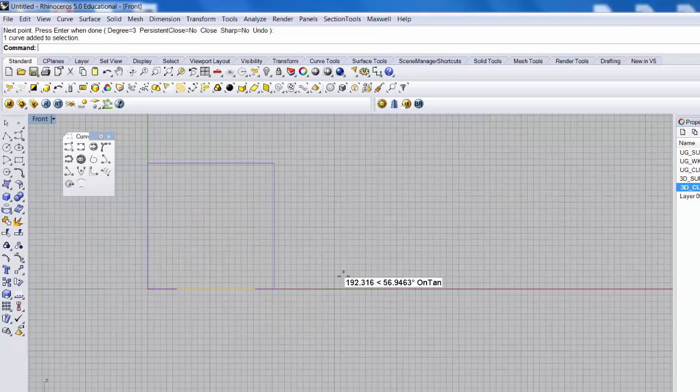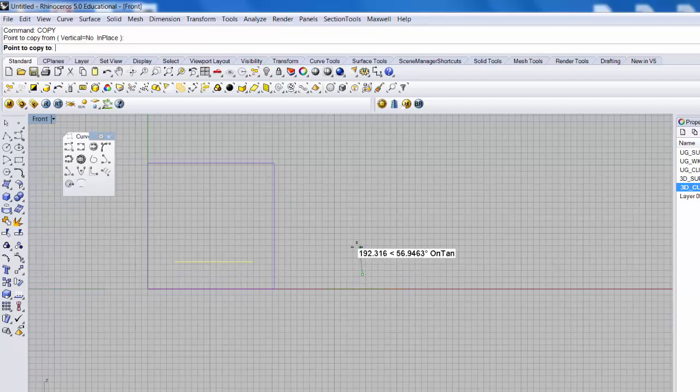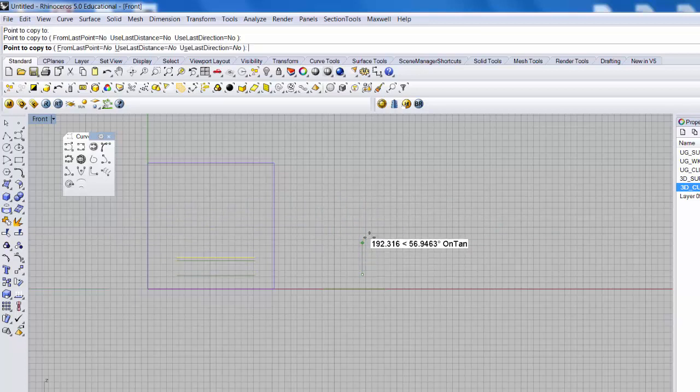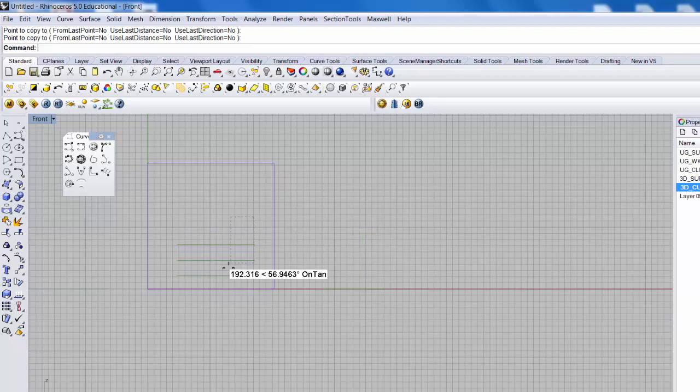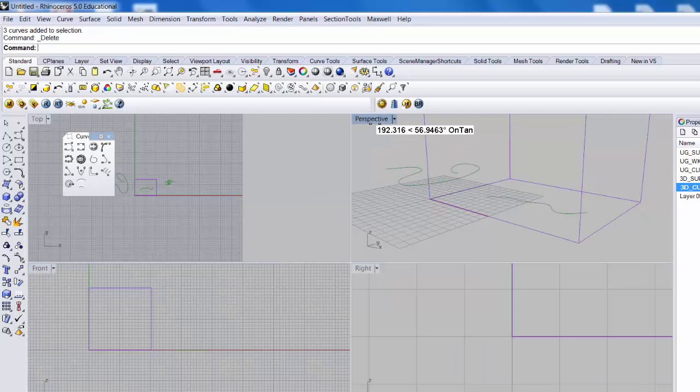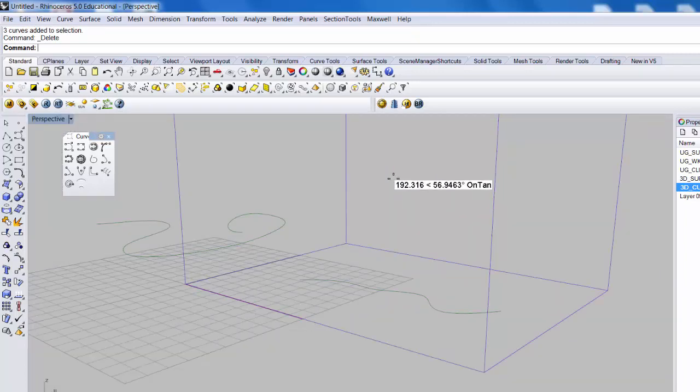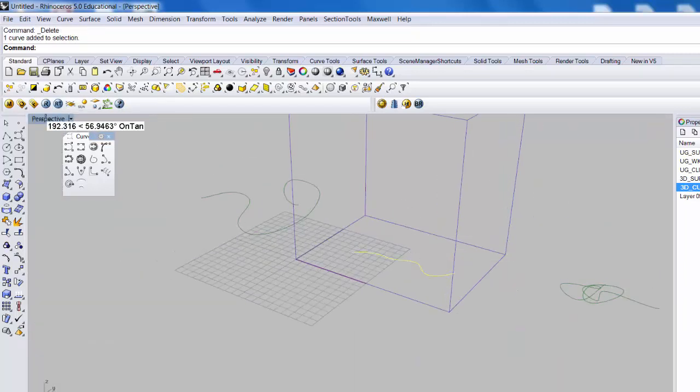And you could array it. There's different ways to do it. I sometimes do things the most obvious way. And now I don't have much control here, so I'm going to go ortho. So I just copy vertically in some kind of intervals. What's actually nice to do, and I'll redo this, whenever you're working with something and you're doing multiples, I always highly recommend, and I learned this from someone, copy in intervals that are regular, so you can always move things back and forth if you want.